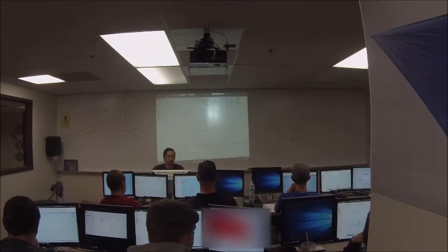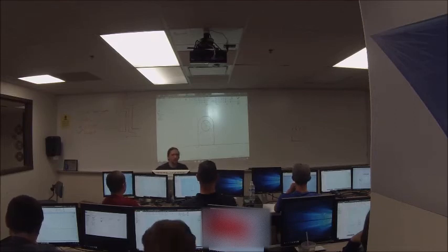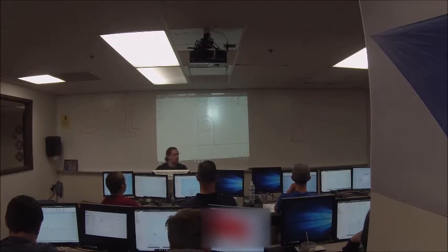When you dimension circles, by default, it does a diameter. But when you do arcs, it does a radius. Just keep that in mind. I think you can change that, but that's typically what you want. You typically want arcs to be a radius dimension. So now, I created those two constraints, deleted it.